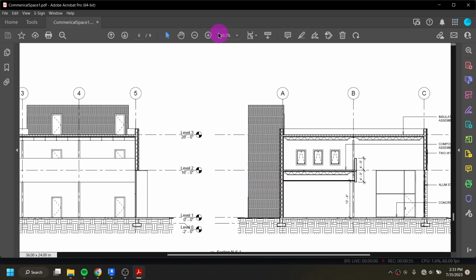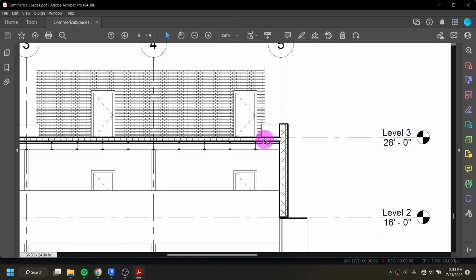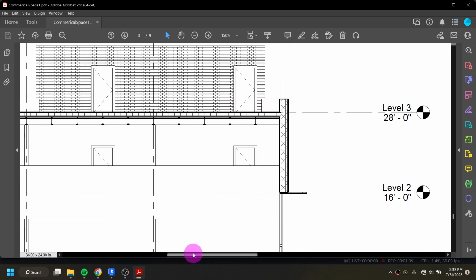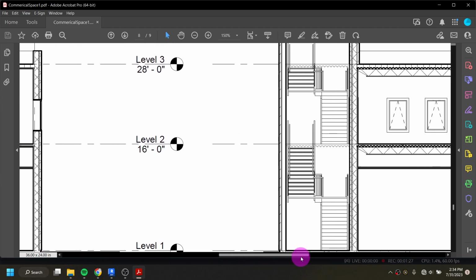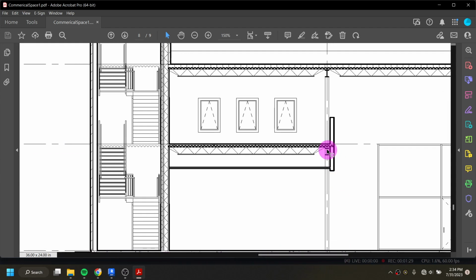There are a few offsets too that we're going to have to do in relation to height for things. So for example, with these webs here, or I guess we can kind of call them trusses or beams that are going across for our ceiling, as well as then if I scroll up for the height to support that loft area. We are going to need to offset them down purely because of how thick the floor is. So when I'm doing offsets, when it comes to those, as well as this I-beam here, I guess it's technically called a W-beam, we're going to have to offset that down as well.